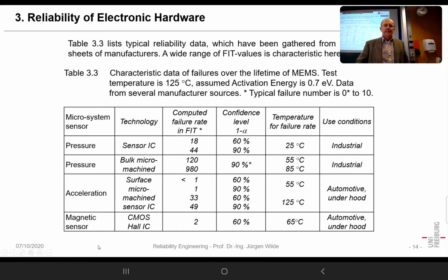And now, if you specify a low value of failure rate, you can only give a lower probability that this value is valid. When you say as a customer, I accept that it is specified with roughly 50 or 49 FIT, I can rely more on it.